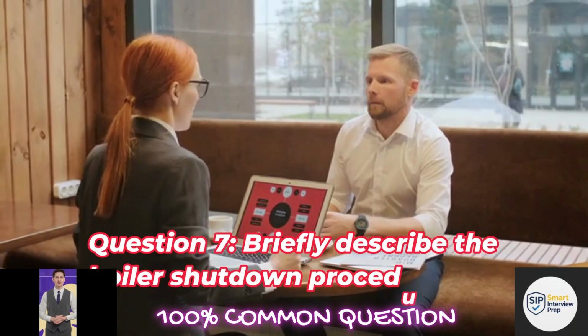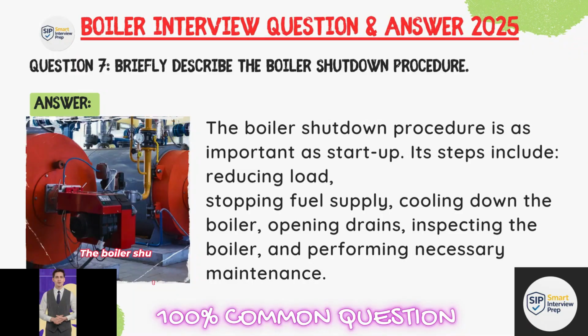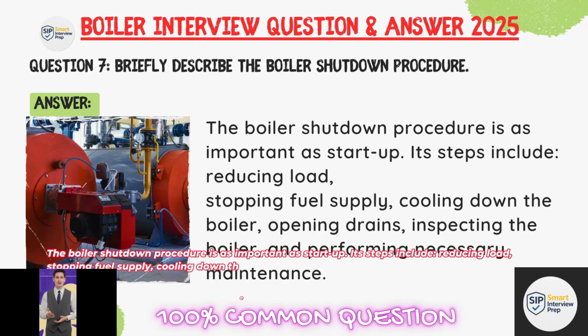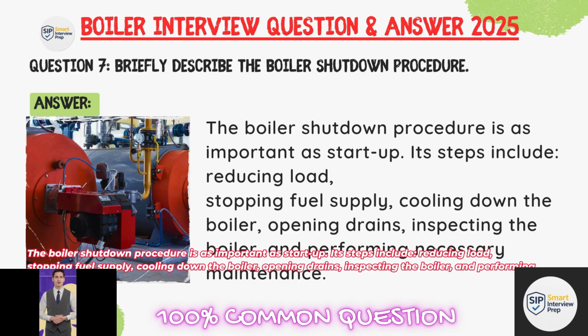Question: Briefly describe the boiler shutdown procedure. Answer: The boiler shutdown procedure is as important as startup. Each step includes reducing load, stopping fuel supply, cooling down the boiler, opening drain, inspecting the boiler, and performing necessary maintenance.